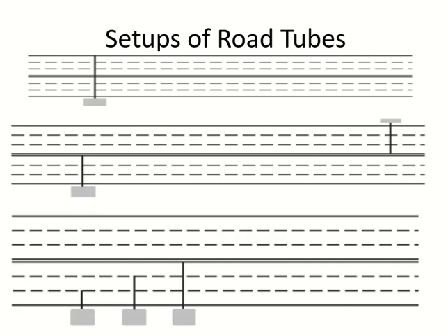But putting the tube for each lane is not so simple, especially if you have a middle lane. Say you have an inside lane and an outside lane, and then you have a middle lane as well. For the inside lane it is easy, as you can see. For the outside lane they do it like this, but I can do it the other way around as well. If I have a median, I can do this inverse: I lay the tube in one lane and put the counter on the median. This can be done as well.